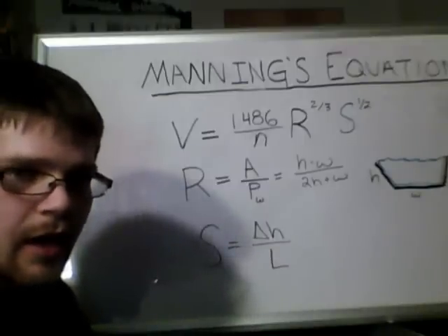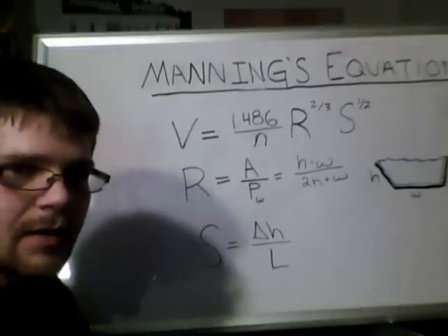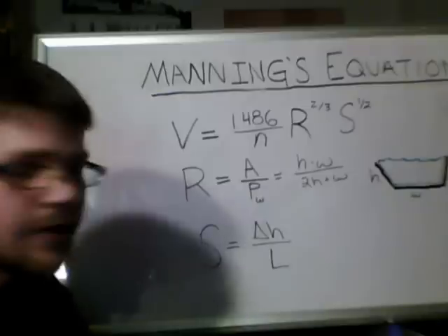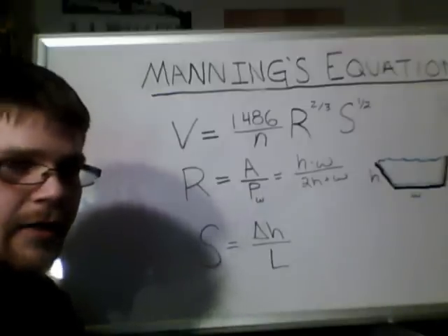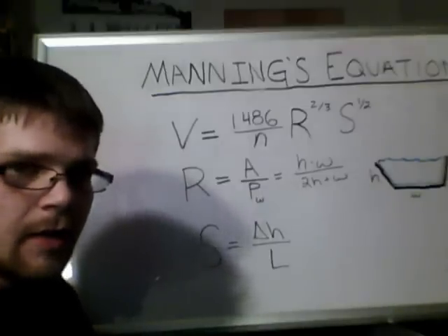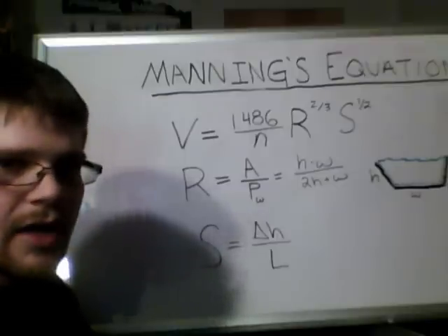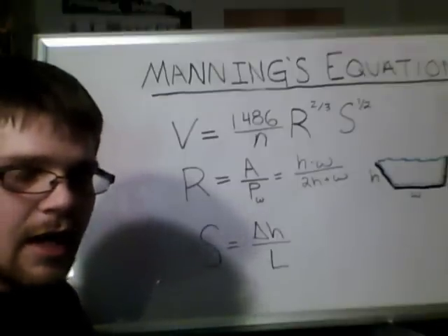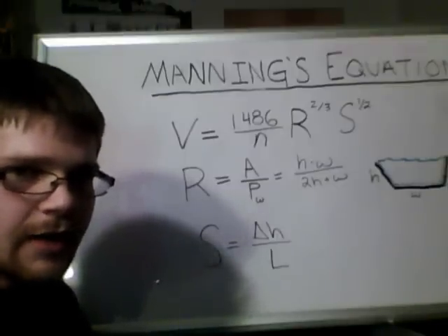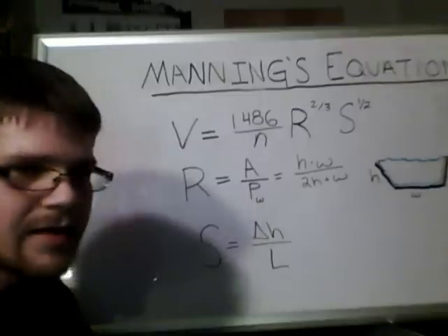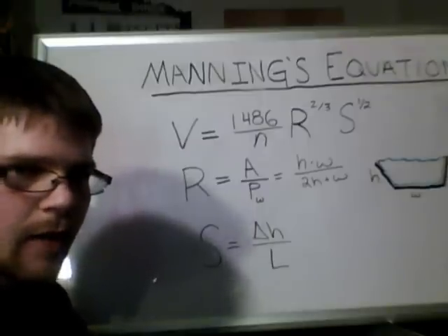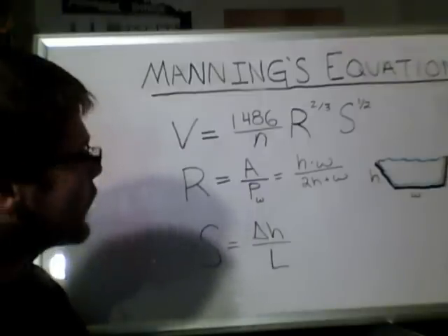If you're wanting to do a very specific analysis, you might even do an analysis specifically on the environment that you're in to get a really accurate Manning's coefficient n. But lucky for us, in most situations, there are already dozens of different Manning's coefficients that have been found through thousands of different tests, and we can use those to our benefit and just apply them out of the table.